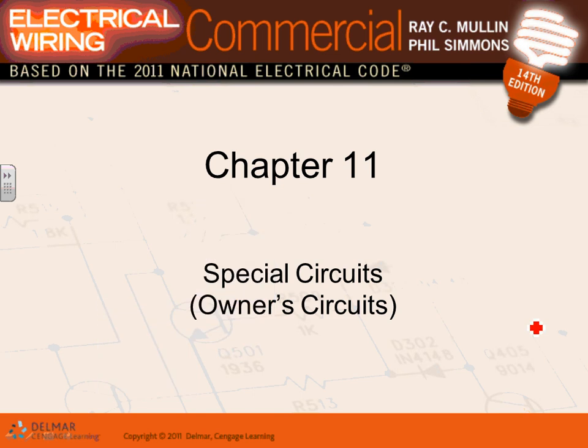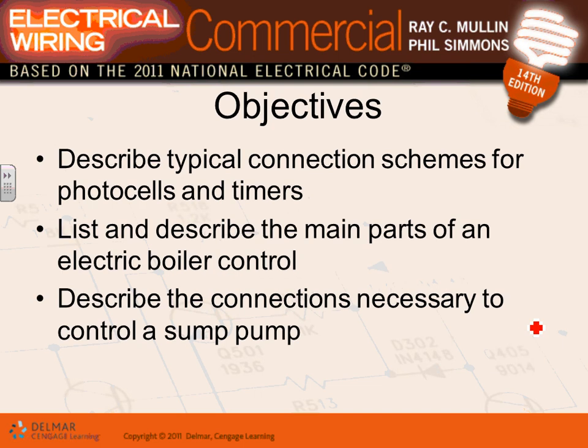All right. Okay, so like I said, Derek, there's multiple tenants in this building, and the common areas for lights and receptacles and heating will be fed from a separate panel, which is backed up by a generator. So this is what we're going to be doing. They call them special circuits, owner circuits, because I want to remind you, we don't have these, Adam, in our building, these special circuits, because the building that we have is one tenant, owned and operated by one tenant, so we don't have to have a special panel for the house or house panel for the common loads.